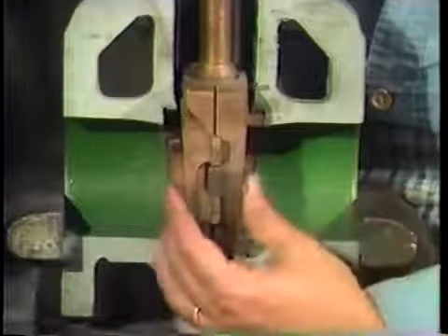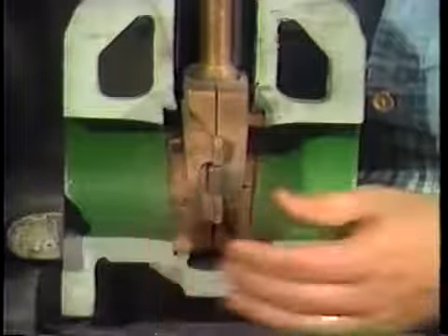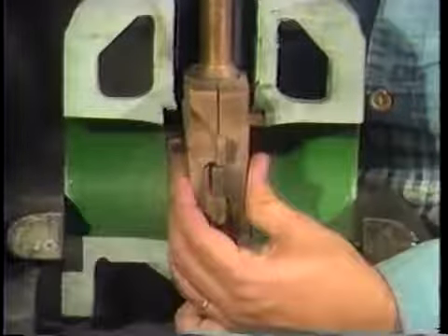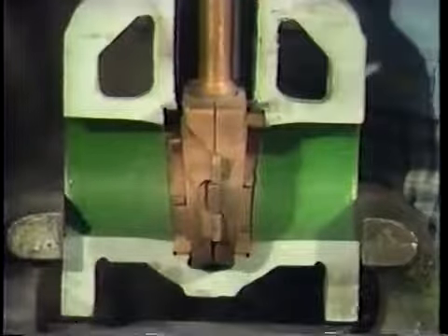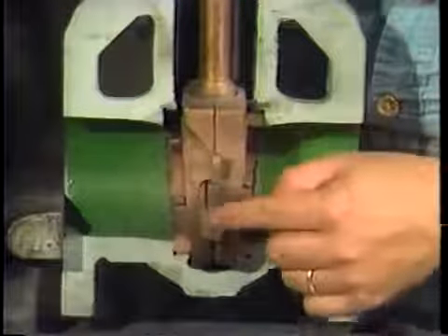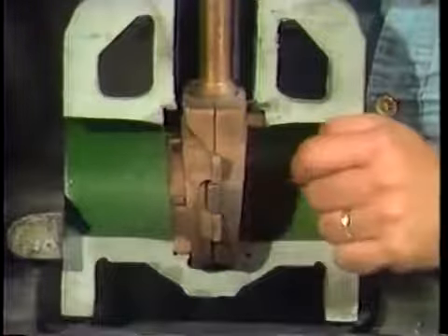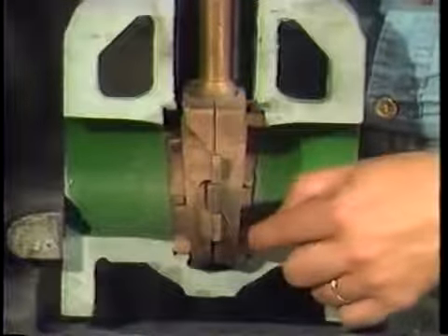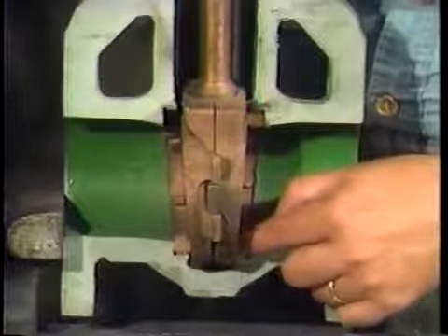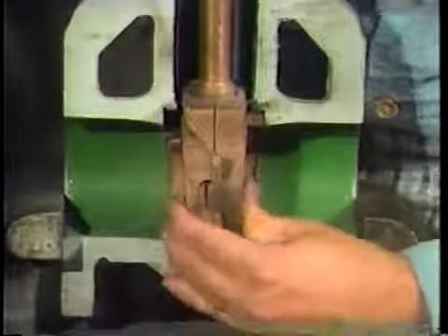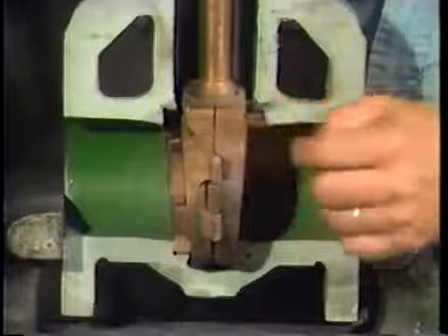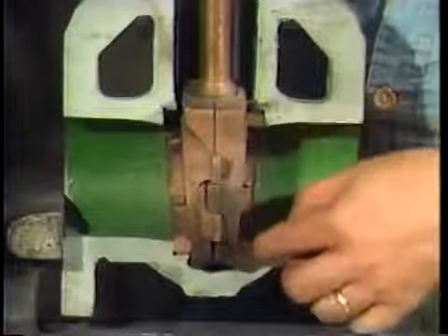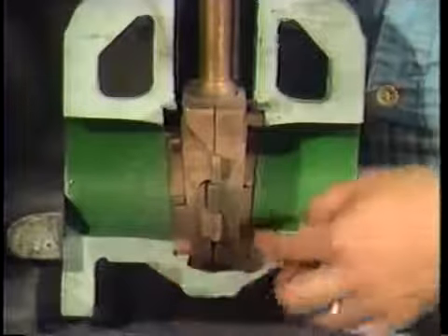Now, gate valve discs, which are sometimes called gates, are made in two ways: a wedge shape, which you see here, and a double disc. The wedge-shaped disc fits between the seats and forms a tight shutoff. It is directed by a set of guides that keep the disc in line as it closes. The disc does not touch the seating surface until the closing point is almost reached, and then the disc is wedged in between both seats. The wedge disc may be split down the center. In this way, each half will rest somewhat independently on the opposite valve seats.